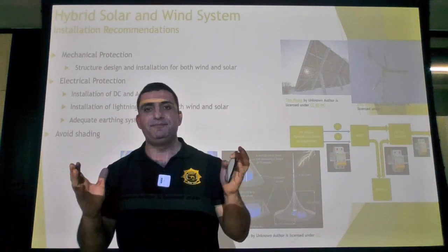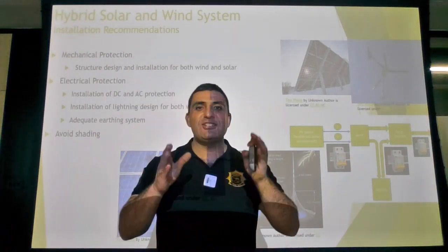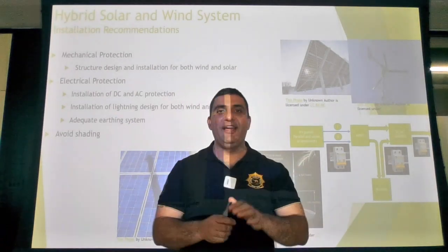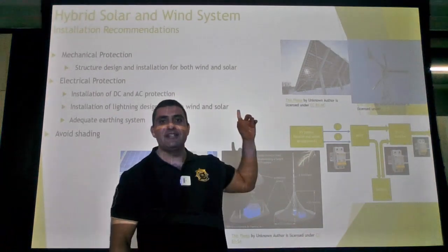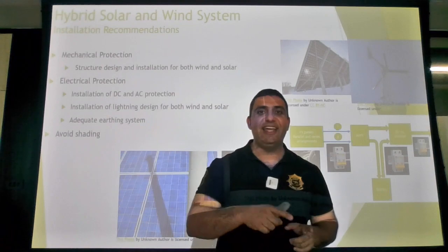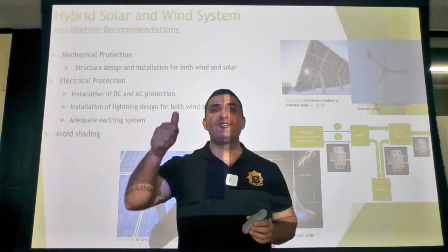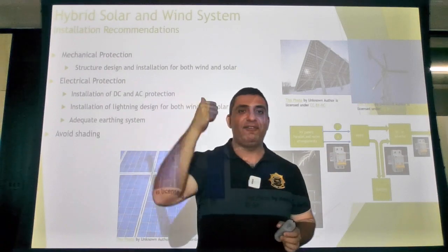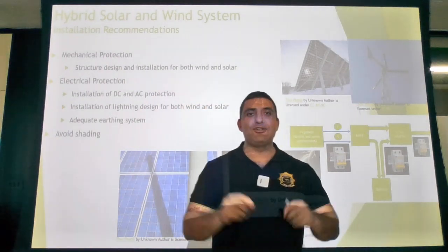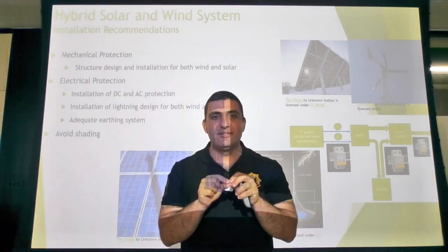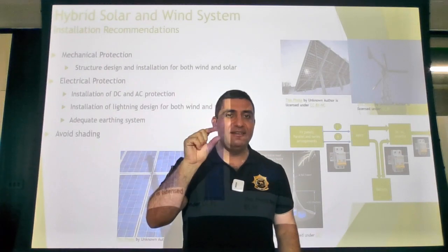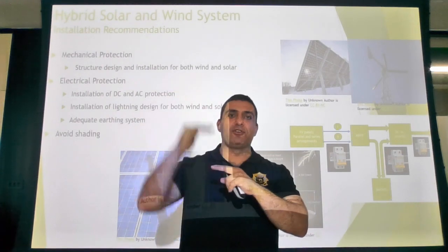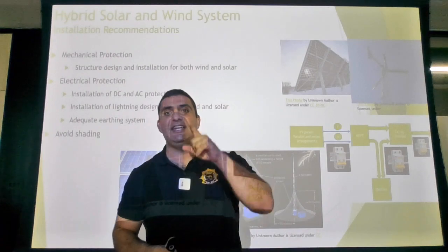To conclude, one of the most important elements when you want to incorporate a wind system into a solar system is that you should check the controller of the wind. Does it have buck boost functions? And also you should check the buck boost functionality. Does it have the right voltage for the right wind speed in your city, in your town?